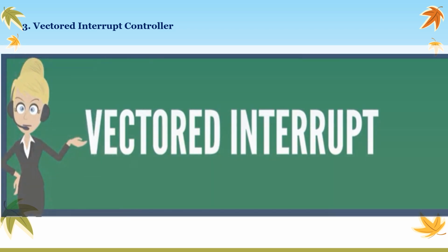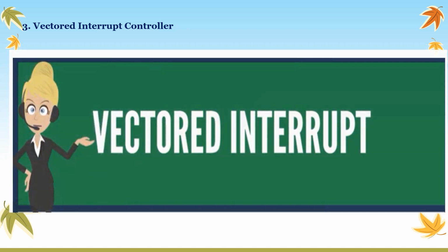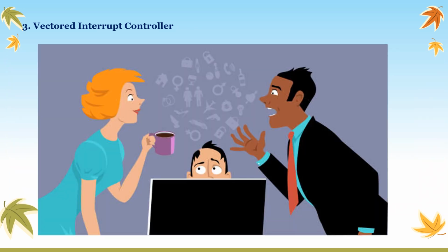It is a special request to the CPU to execute a function, a small piece of code called the ISR, when an interrupt occurs. When an IRQ arrives at the CPU, it stops executing the current code and starts executing the ISR. After the ISR execution has finished, the CPU gets back to where it had stopped.